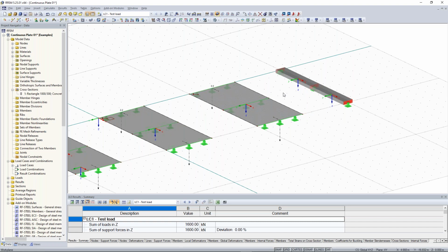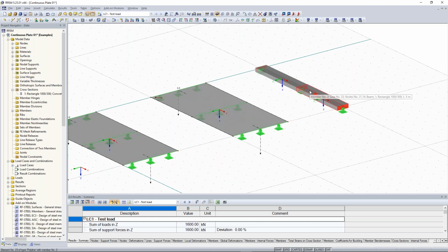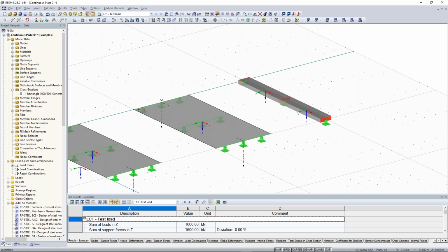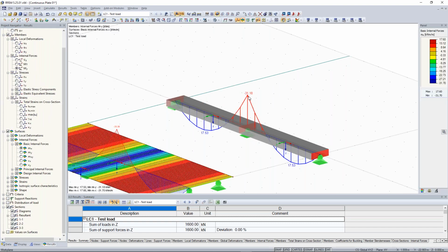Now, normally in the study, you do some hand calculations. That's pretty common. And therefore, you also use some tables or calculators and so on. And when you calculate the support moment of a two-field beam or continuous beam, you will maybe get other kinds of values. So let's watch the results again. And normally you would get here a support moment of 31.25 kilonewton meters. Yeah, but in this case, just 31.18.